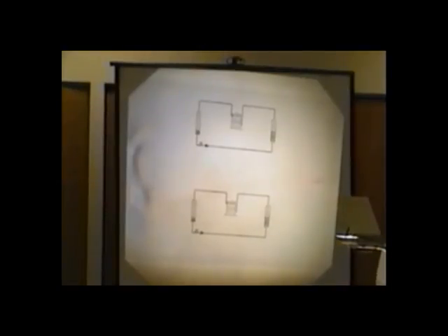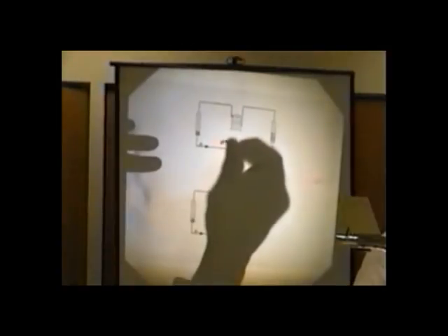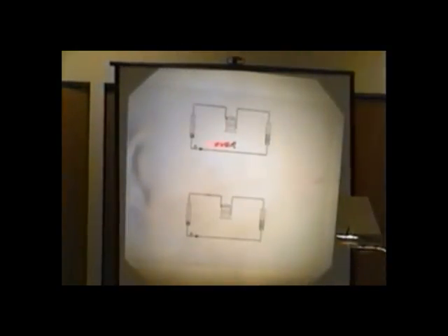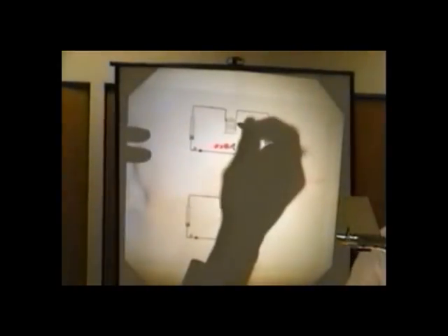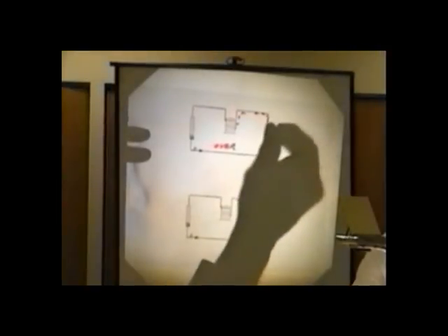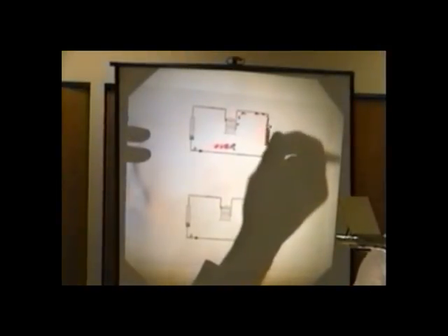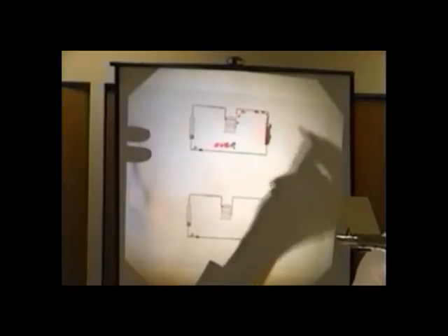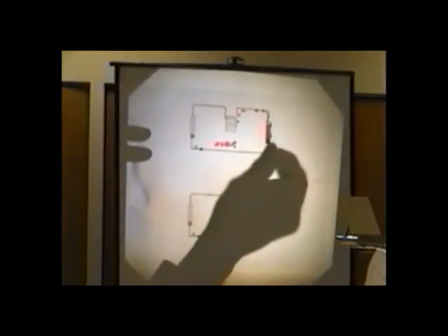Let's do an overcharge. Is the pressure going to go up or down with an overcharge? Goes up. Lots of liquid now. See it? Lots of liquid. Very little vapor.